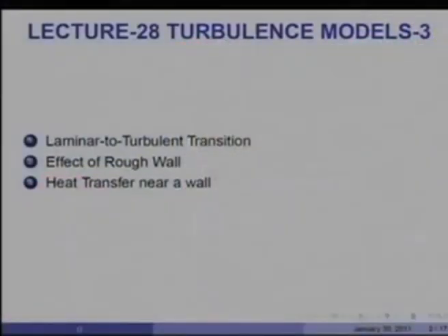But as I said, these turbulence models with low turbulence Reynolds number require fairly heavy computation expense because of the very large number of grid nodes required close to a wall. And therefore, at earlier times simpler approaches to modeling transitional regime were adopted, and my purpose in this lecture is to really look at laminar to turbulent transition in a little bit more detail.